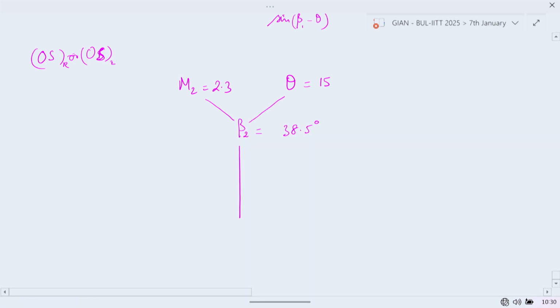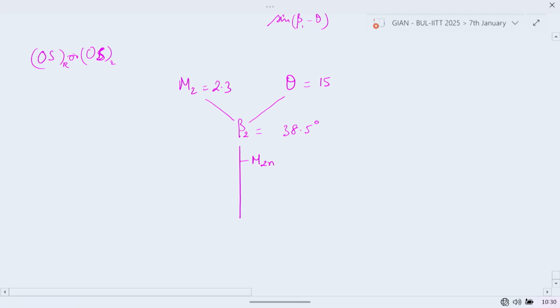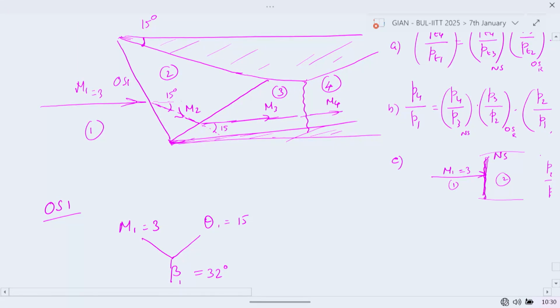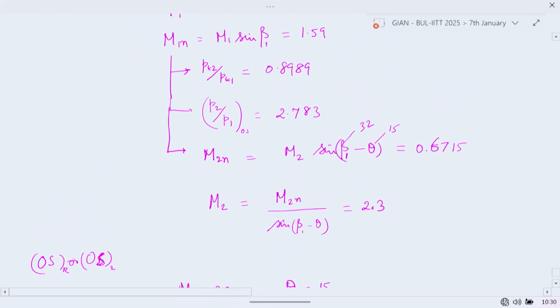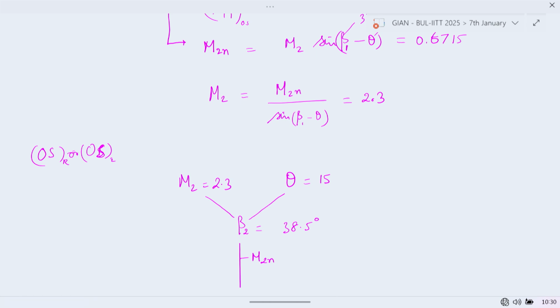So from this we can find... The cowl angle is 5 degrees. Oh yeah, the cowl. I didn't notice, this angle is given as 5 degrees, so we need to account for this, otherwise the flow will hit the internal cowl surface.